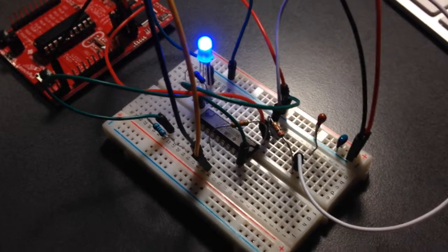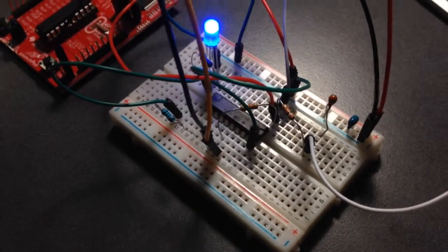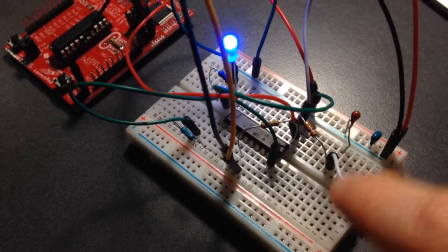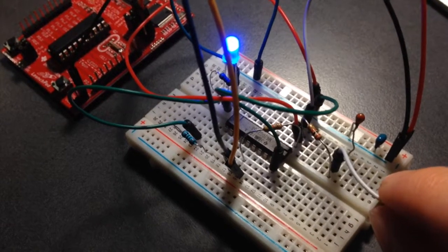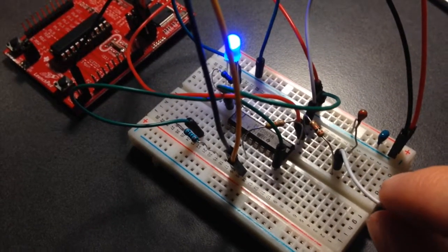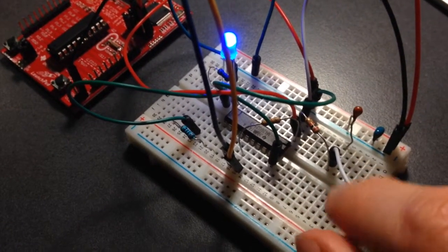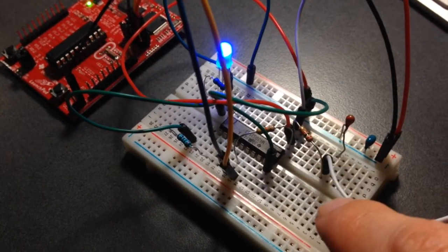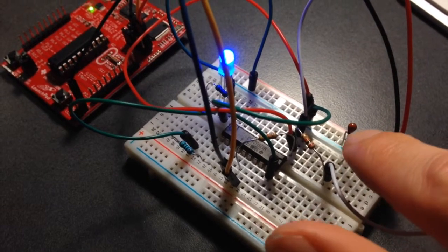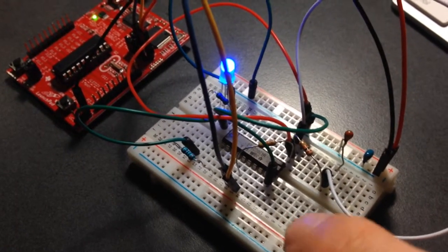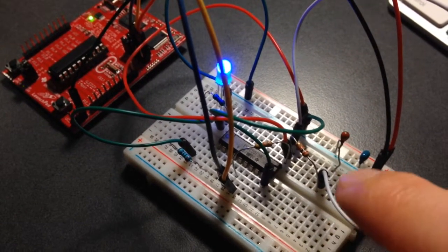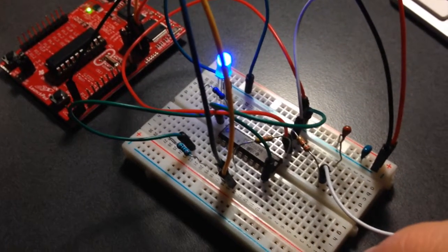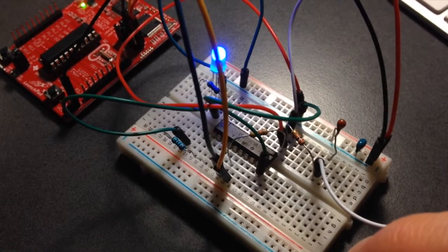Over here on the right, we have the thermistor, which is currently bridged between this white wire, which is our measuring wire that goes into one of the ports on the MSP430, and ground. Right here we have a 20 kilo ohm resistor, which is bridging between VCC, the measurement, and then the thermistor to ground. What this does is it helps ensure that the voltage drop across the thermistor never exceeds 1.5 volts, at least in the range that we're measuring.